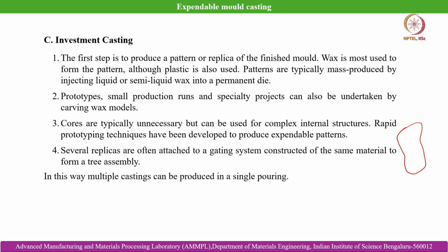So, what benefit does it give? So, if we develop this wax based pattern or polymeric patterns by polymeric AM or additive manufacturing or 3D printing route, then we can really develop some complex contoured patterns of the components which are further going to be produced via the investment casting route. And if we can produce the patterns by this AM route, then it can save us a lot of time to make the complex contoured injection molds to get these polymeric patterns made. So, thereby it can save a lot of time and also to some extent cost.